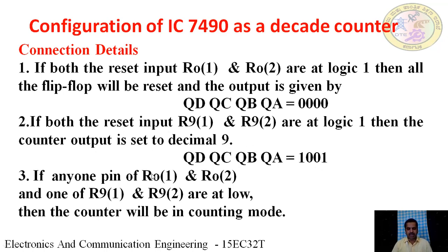If any one of the pins R01 and R02 and one of R91, R92 are at low, the counter will be in counting mode.